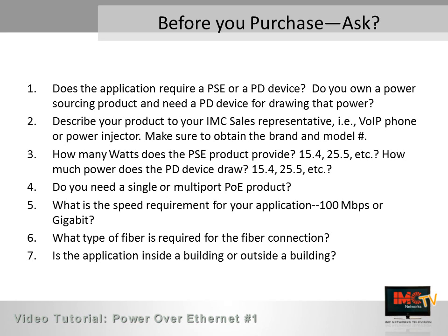The third question would be, how many watts does this PSE product provide? Type 1 or Type 2, for example. And conversely, what if it's a PD device? How much power does it draw? 15.4, 25.5, etc. The fourth question is whether the customer needs a single or a multi-port PoE product. For example, in the application showing the 2 PTZ cameras, they both needed Type 2 power and required 2 ports.